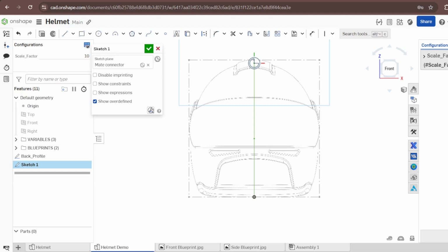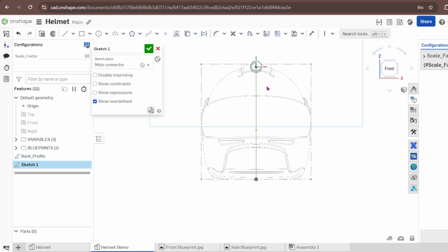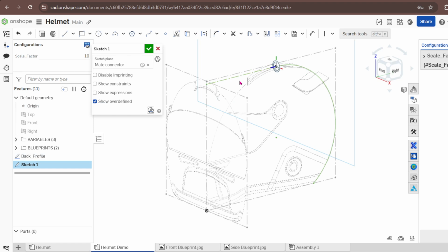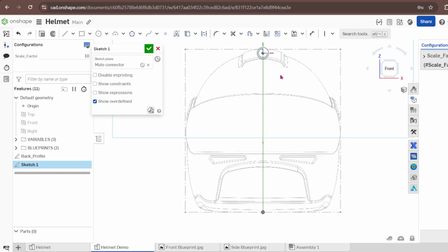And now, for me not to trace this curve here, first thing I need this point. I'm going to select that point and project it. Why? Because I want to make sure that the sketch terminates at this point. I'm connecting this to the sketch because I'm going to use a surface and I need them to terminate at the same point. And also terminating at this point, when you start now to scale your model, it will also scale. Okay?